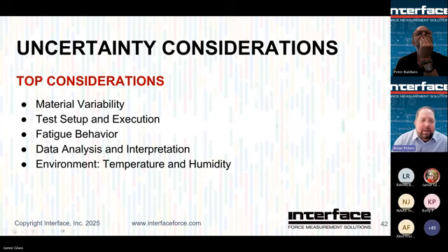So uncertainty. So you're going to have some level of uncertainty in the test. With any test setup, usually it's going to come down to your load cell performance factors and things of that nature. But you can certainly have in a fatigue test scenario additional aspects. Are you getting any material availability, variability, or any change in mechanical stiffness of the rest of your fixturing?